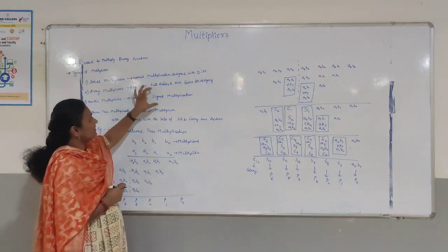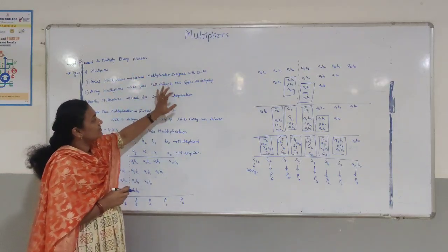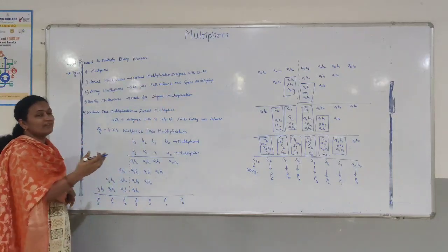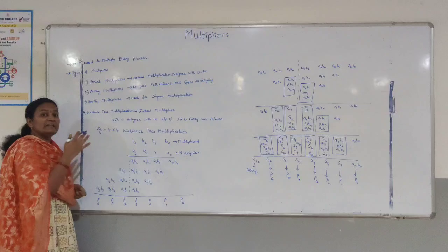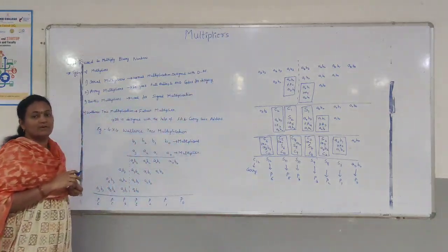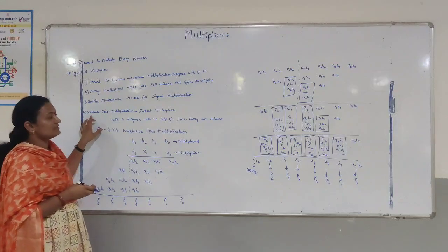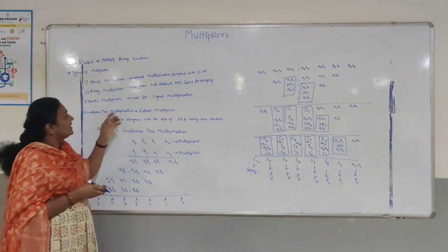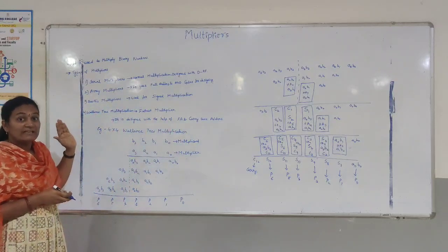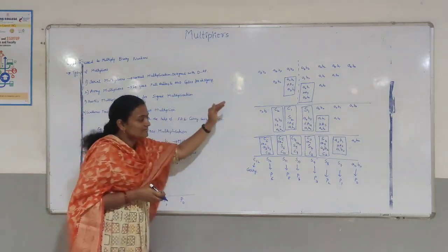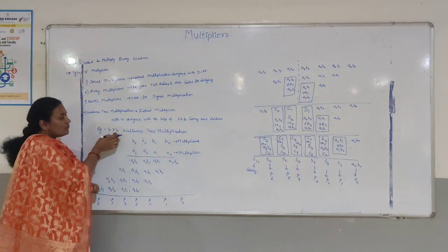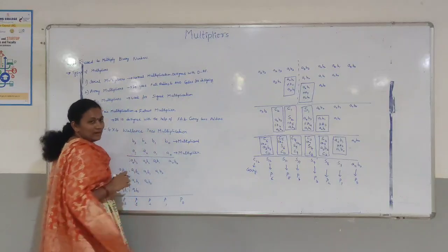In the other three, when we are designing, they use different types of flip-flops and full adders. The carry is propagated to the next adder, so the delay is more in these three multipliers. When you go for balanced multiplication, it saves the carry and gives it to the next adder for the next multiplication process. Now I will explain the 4 into 4 balanced multiplication.